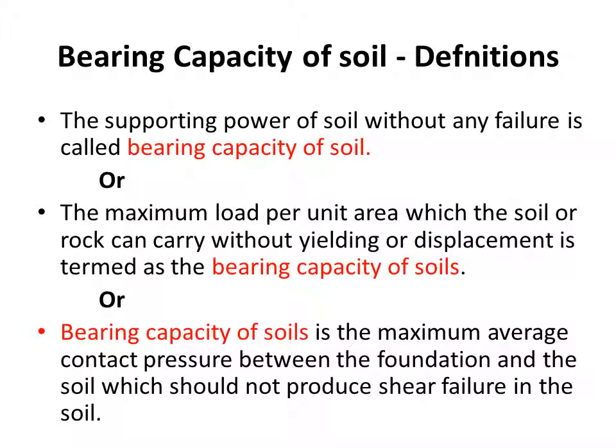Now let's see the definition for the bearing capacity of soil. The supporting power of soil without any failure is called the bearing capacity of soil, or the maximum load per unit area which the soil or rock can carry without yielding or displacement is termed as the bearing capacity of soil. Or bearing capacity of soil is the maximum average contact pressure between the foundation and the soil, which should not produce shear failure in the soil.